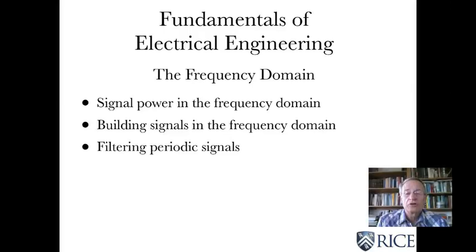So in this video we're going to continue our discussion of the frequency domain and thinking about signal structure in the frequency domain in addition to the time domain. We're first going to prove something called Parseval's theorem, which shows us how to compute the power in a signal entirely in the frequency domain. In many cases it's easier to compute it that way than directly in the time domain.